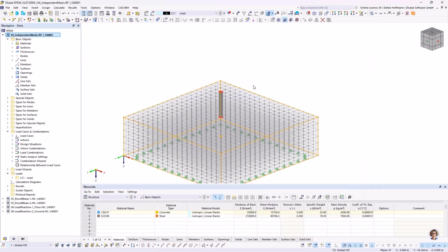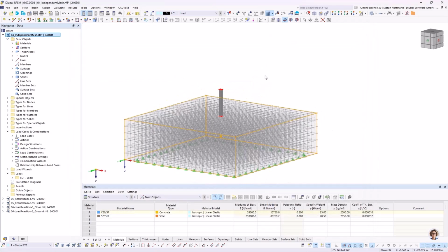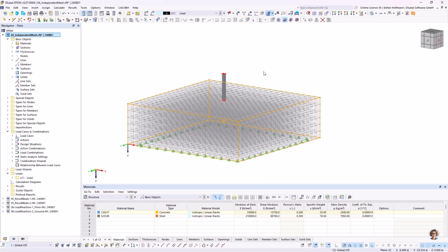These settings will most likely allow you to have a better optimized mesh and shorter calculation times. And of course the forces and the objects will still be connected with some settings in the solver and distribute the forces into the connected objects, but now without the need of the same mesh.